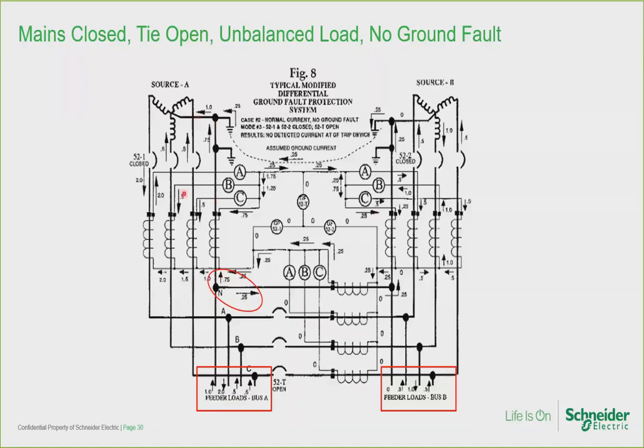What causes that parallel neutral path? If you look at the dotted line right here between the grounding electrodes, at first it looks like current is flowing through dirt between 2 grounding electrodes that ground the transformers. That is not what's happening because dirt represents too high of an impedance to low voltage currents. This dotted line, in fact, represents the ground bus inside the main switchboard.